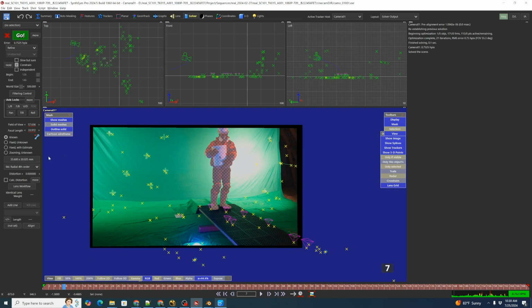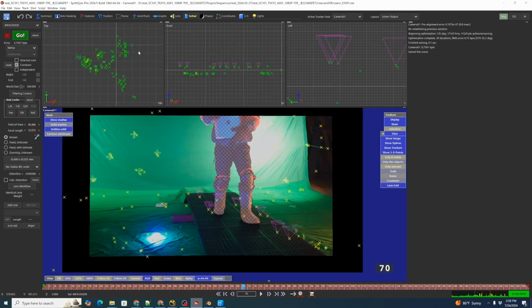Now, an important thing is, let's go look at, I'll hover over here, and we can see that we have our original sensor size, 35.6, but now below that, we have an effective size of 37.8. And we're going to want to remember that number because that is the sensor width that we're going to send to Blender. That is how we're going to handle overscan in this workflow. All right, so now that's working. Hit save. So now let's go to our Blender export.